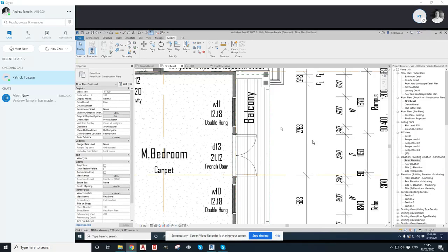That dimension was referencing the railing in its current state, but because we were making it smaller, that middle post was controlled to be in the center of that dimension. So when the railing got smaller, the post moved. We didn't want that.